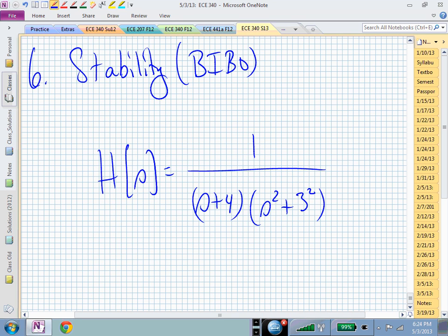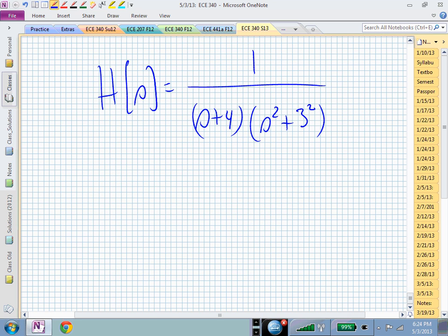It should probably be factored in terms of quadratics. Now, those quadratics may be 2 real roots, so you'll want to know the quadratic formula if you don't have it. But now, if you're used to looking at this, hopefully you're now seeing that that second factor corresponds to poles right on the imaginary axis. And what does that mean in terms of BIBO stability?